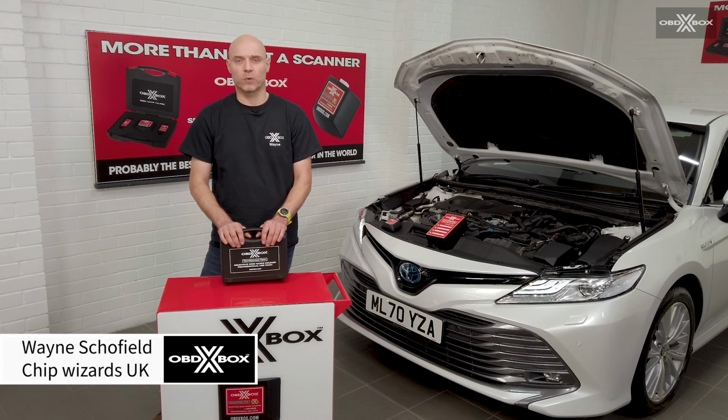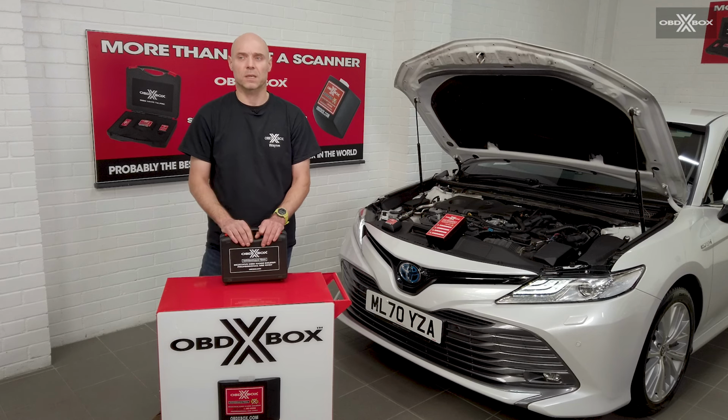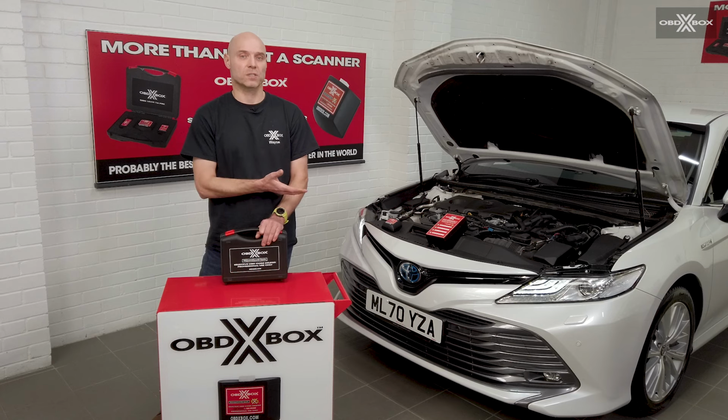My name's Wayne Schofield. I've been working with engine management systems since the 1980s. Through that time, I've seen the evolution of the diagnosis of faults with engine management systems. In the early days, you were using external devices, so multimeters, oscilloscopes. They evolved into parallel systems, such as the auto-diagnose parallel system that worked on a breakout basis. And eventually, we had onboard systems, where the ECU itself did its own diagnosis and stores faults as code numbers. It's retrieving those code numbers that gives us the fault codes that we're familiar with today.